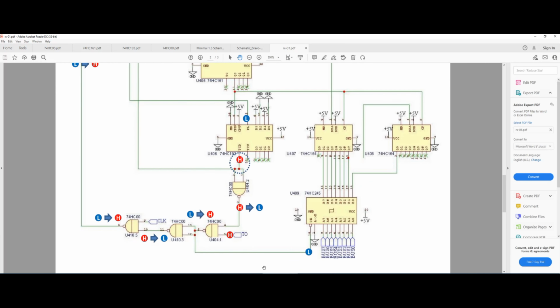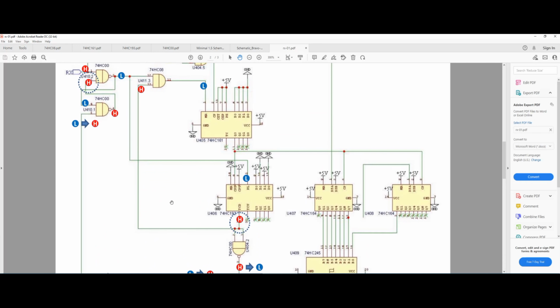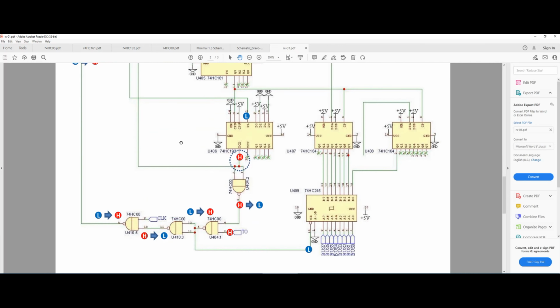So that means that as soon as you set the TO signal high, two important things are going to happen here: one latch and one high signal. First, we're going to latch a high here, and second, we're going to set that signal to high. But still, our counter is not active because this AND gate is still not active, right? So when the signal goes high this time around, those signals are going to transition.